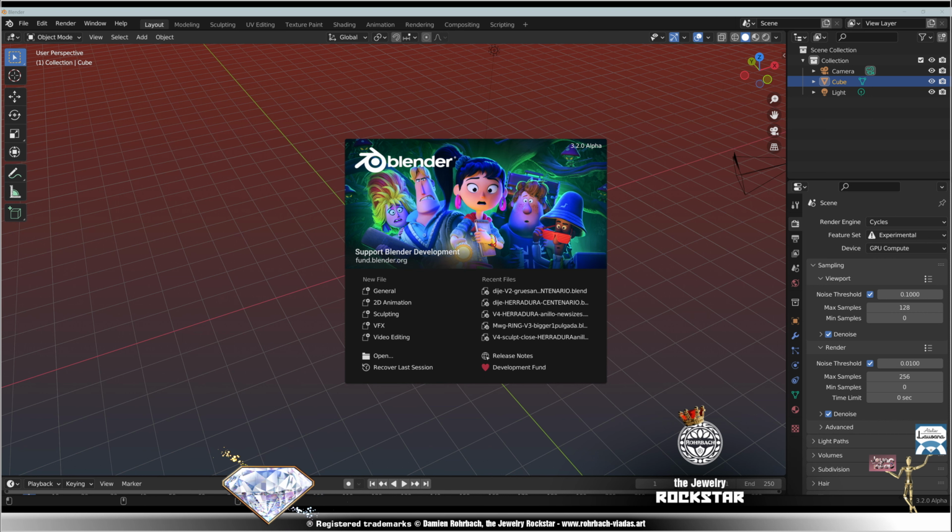And this is quite nice. Let's try 75. Now beware with the smooth, because it reduces your mesh. It erodes your mesh because it's smoothing the mesh. But because I gave an extra thickness and an extra height to my bezel at the beginning, and I talked about that enough, it's always better to have some reserve, some extra to do this. So now the bezel is looking great.